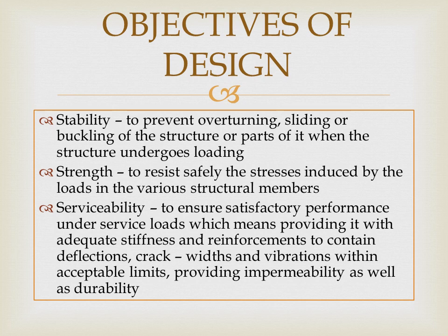The last one is serviceability. That means we have to ensure that it has satisfactory performance under service loads, which means providing it with adequate stiffness and reinforcements to resist deflections, and to keep crack widths and vibrations within acceptable limits, providing impermeability as well as durability.